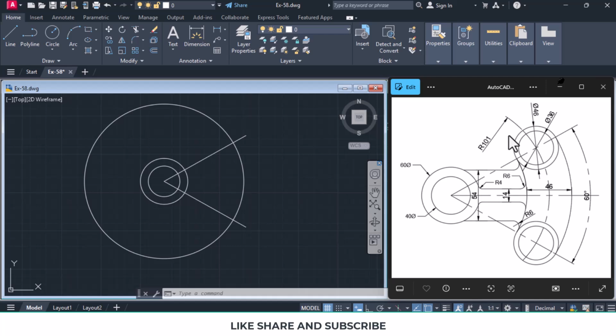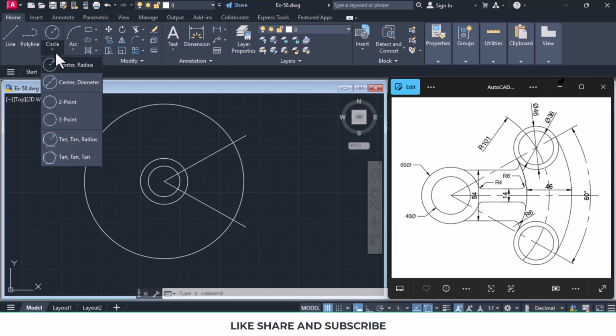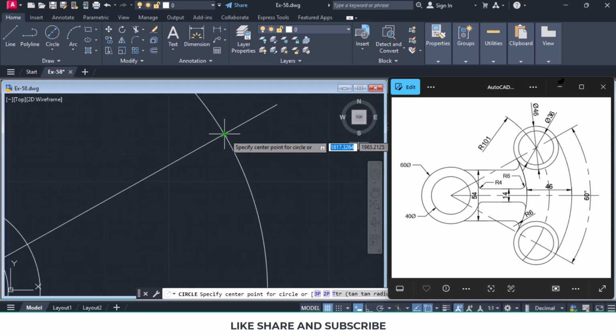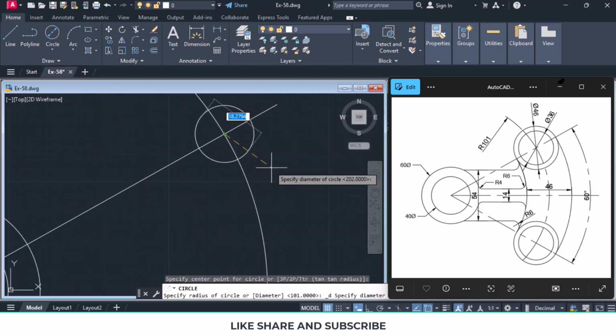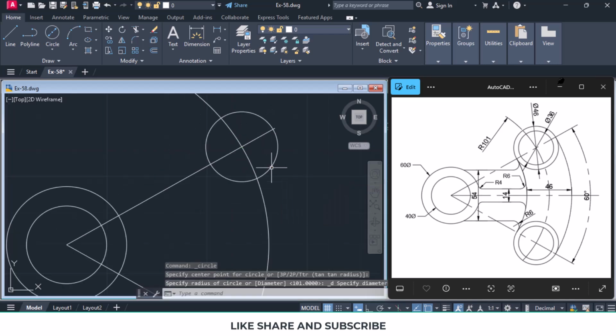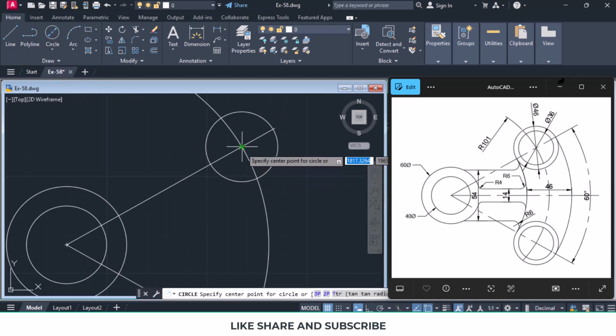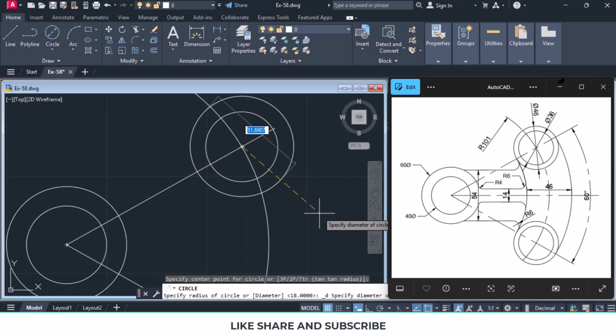Now with this intersection as the center point, we'll draw a circle first of 36 dia. So we select circle center diameter. We click on the intersection over here and draw a circle of 36 dia and hit enter. Then we want to draw a circle of 46 dia. So again circle, center diameter, same center point, and diameter we'll give it as 46 and hit enter.